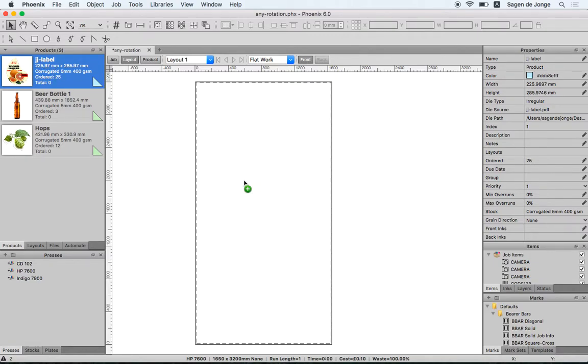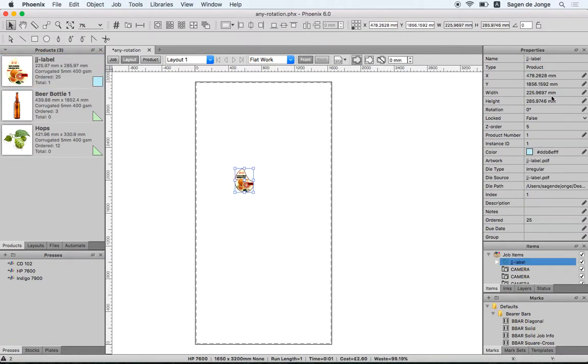So now for any product, you can go and scale the width and height. So for example, I can go here and type into the width parameter here. I could type in 500%, and I could do the same for the height, type 500% for that. And once I do that, now this item has been scaled by 500%. You can see you can scale the width and height separately. I could enter a percent value or just the actual exact value I want, so 600 millimeter height, and so you can scale your items like that.